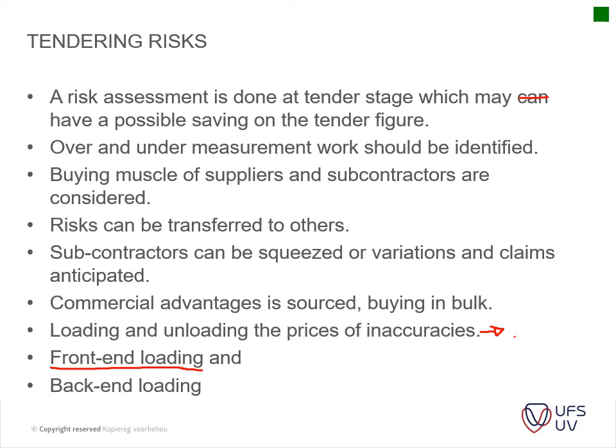Obviously, you do that discreetly, and you only make slight changes at the front, because the bigger you're loading at the front, the higher your risk will be, because when you remeasure your work on site, your excavations might be much less than you anticipated, in which instance you will actually lose on your contract, because now your back end items will not have the necessary rates or bulk of finance to carry you through the project.